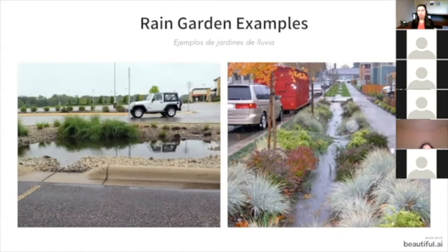In Arizona, they have utilized the strategy of these basins, or rain gardens, that fill up with the runoff from the road, and then also from the sidewalk, different inlets from the different buildings. But then, as you can see, there's parking right next to it. One of the issues they were encountering is that people didn't want to fall into the basin. If you step out of your car and fall into a sloped side.